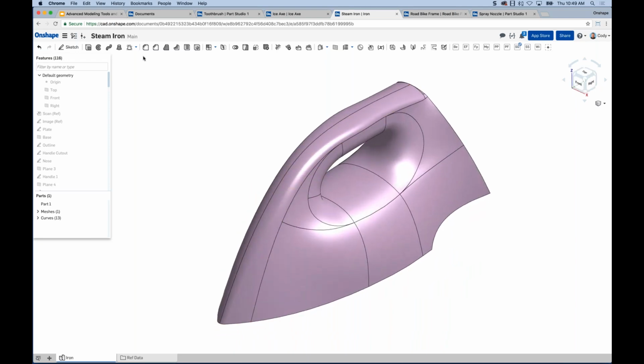The question that often gets asked there is, how do I take a shell or a surface model and convert it to a solid, right? Enclosed to solid. And the answer is enclose. You'll find it again under the thicken command.